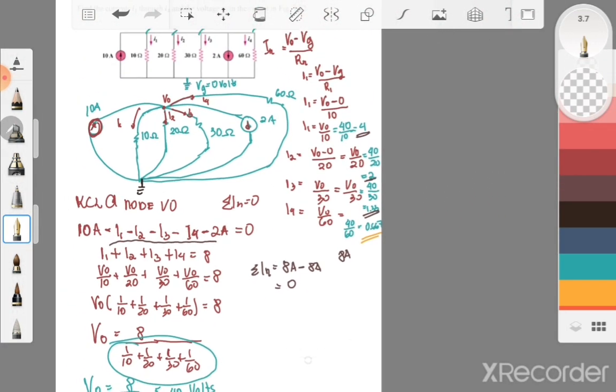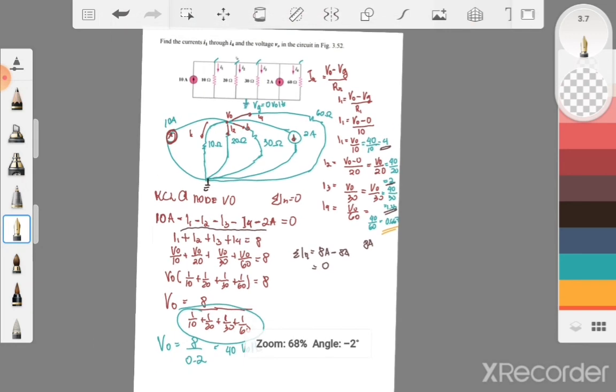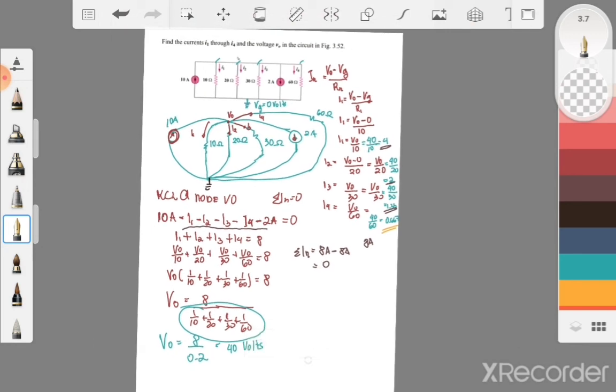Okay? So these are our currents. So, remember the steps. If no ground is given, create a ground before solving. The ground will be your datum, which is equal to 0 volts, and then indicate the necessary voltage at the nodes. And then select or assume the direction of your current.